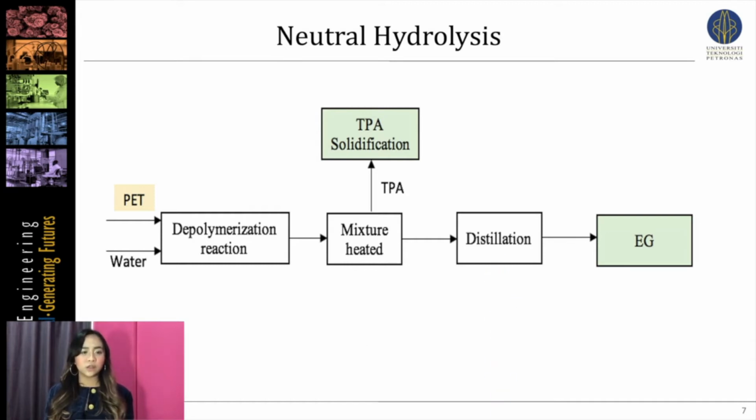The heating of the solid TPA is then cooled to temperature below the dew point of TPA and the solid TPA is formed. This method is very environmentally friendly because the production does not require any use of unsafe chemicals for the environment and does not produce any harsh byproducts. However, the purity of TPA produced from this method can only be achieved around 70 to 80%.